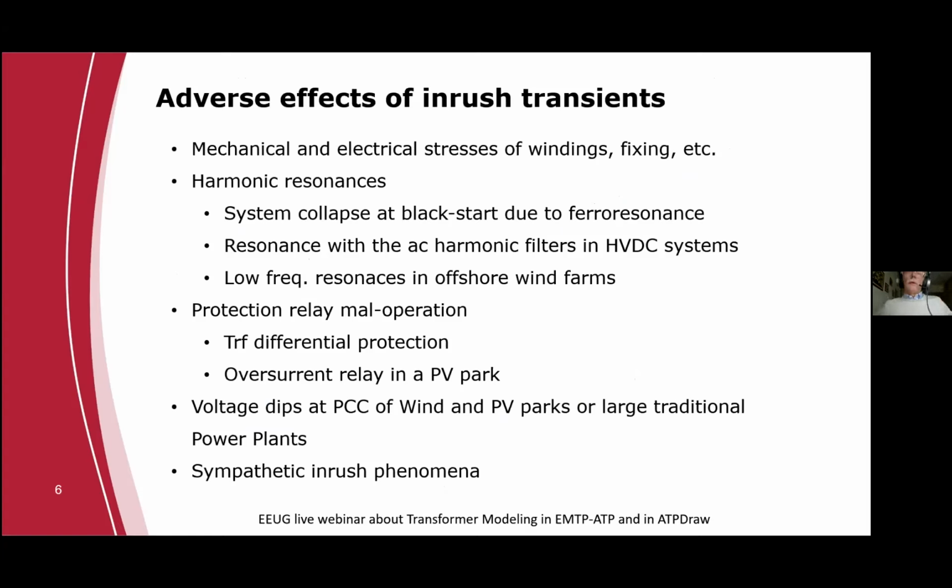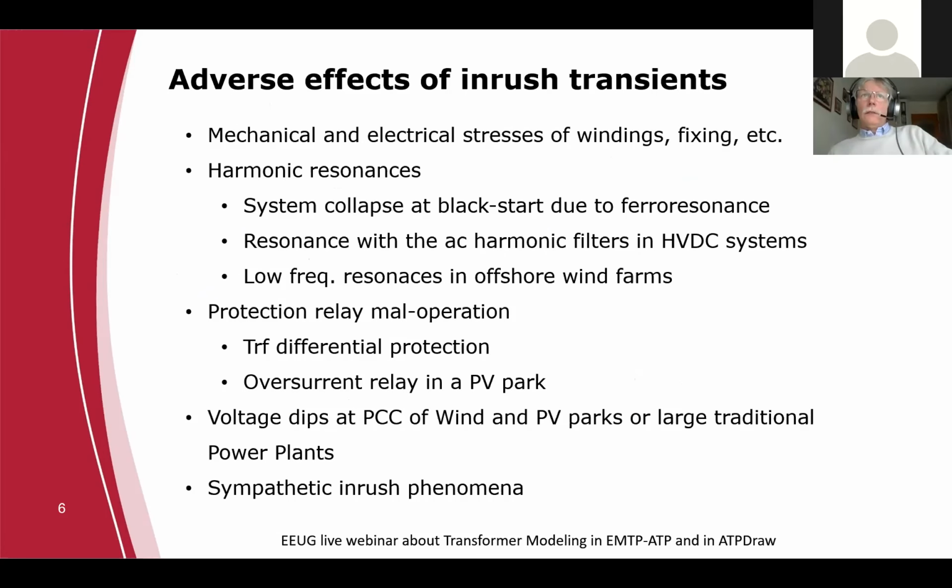What are the consequences if we have a nonlinear transformer, or if we consider the nonlinearities? If we experience a high inrush current, on the other hand, it will have some mechanical and electrical stresses on the windings or the fixing of the windings. If we have a nonlinear transformer, it can resonate. Mostly it can resonate with the capacitances of the grid.